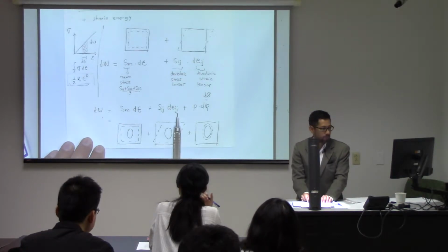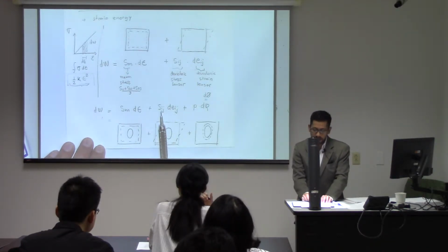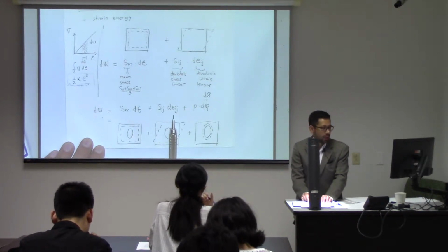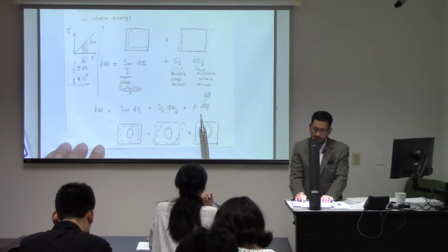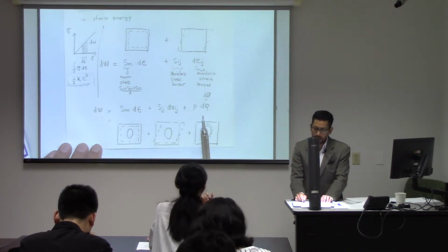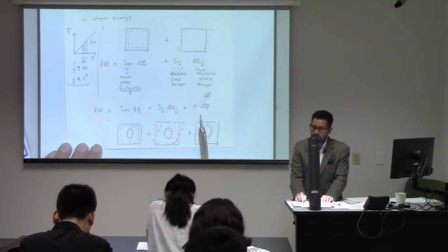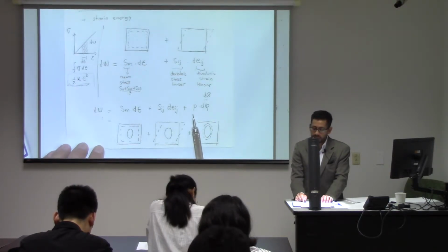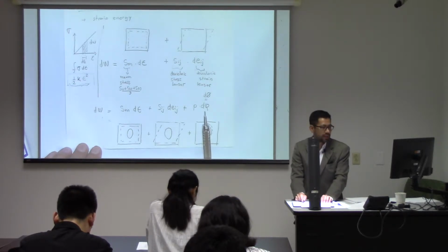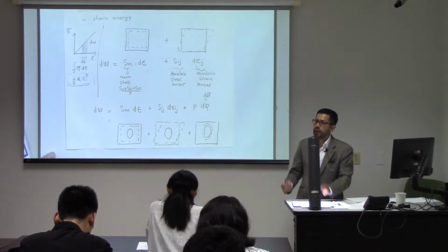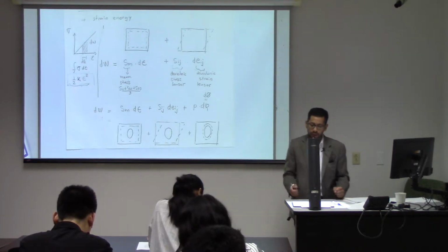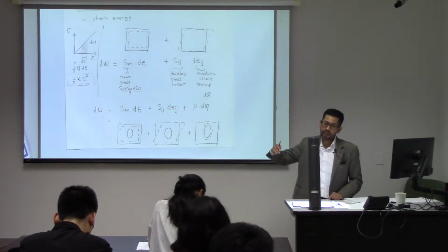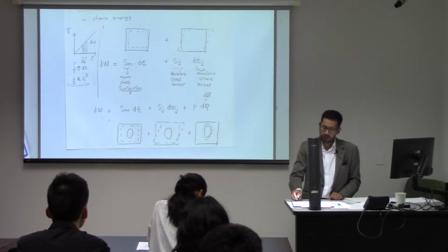And this is the deviatoric stress tensor. This is the deviatoric strain tensor. And one more, we can add also energy to this fluid-filled porous solid with pressure, pressurizing the fluid inside. And that's also going to be quantified by the change of porosity. If I change the porosity, I also add strain to the solid, which is going to add even more strain to the porous solid. So we have the energy that comes from the fluid itself and the energy that comes